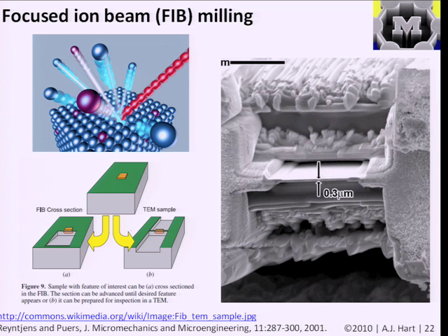Incidentally, in microelectronics fabrication, one of the most expensive components is the mask. Because they're creating such fine features, they want very low defect densities. They have to create very accurate masks for really big wafers. And so electron beam lithography is often used to create that master, and focused ion beam milling and focused ion beam deposition of materials is often used to repair defects in the mask. Or if, say, there's a particle on the wafer and it damages the mask and they detect that by examining the circuits, they often take the mask and repair it with these kinds of lower throughput techniques. So it's kind of like a nanoscale repair process that complements the larger area methods.